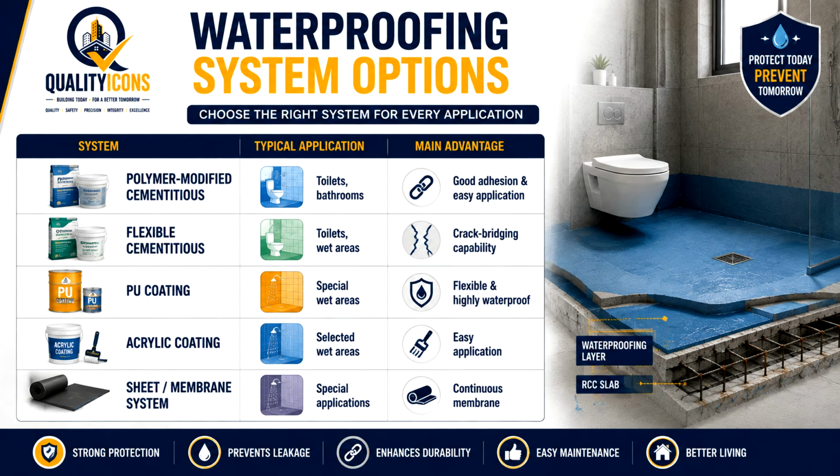Coming to polyurethane or polyurea systems, these provide high flexibility and strong waterproofing performance, but their substrate and application requirements need to be very carefully controlled.